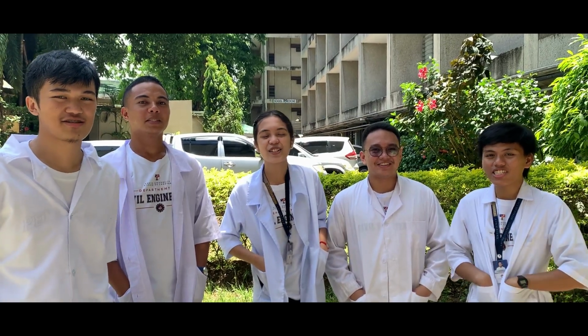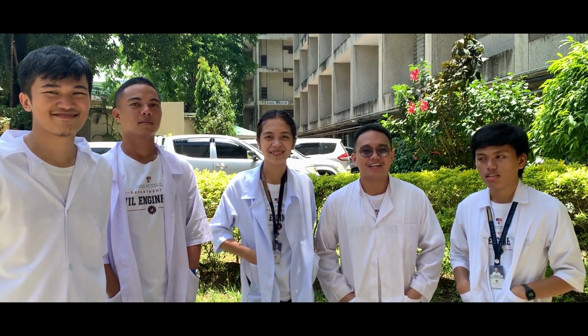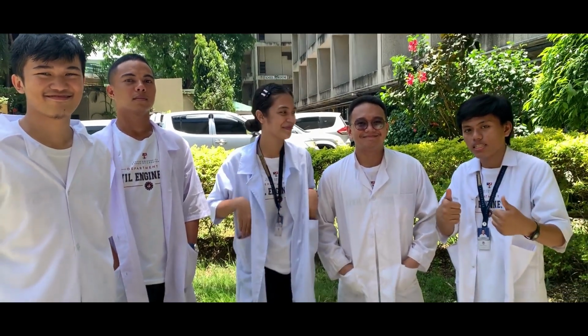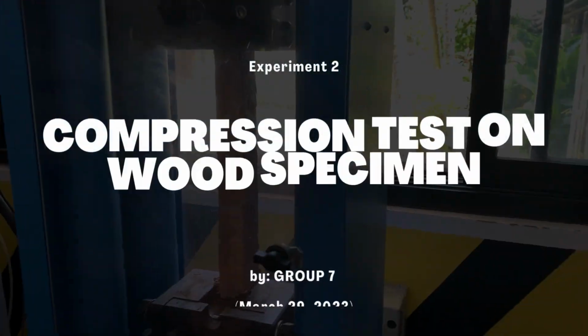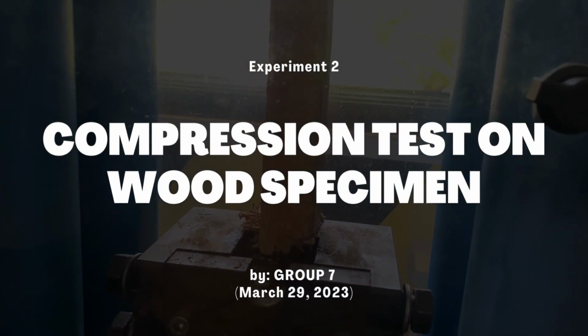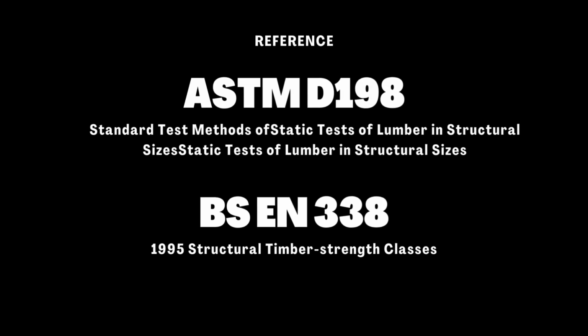Good day, engineers! Today we're going to perform a compression test on wood specimens, particularly mahogany, cocoa lumber, and Gmelina species. Laboratory procedures and specifications are in accordance with ASTM D198 and BS EN 338.